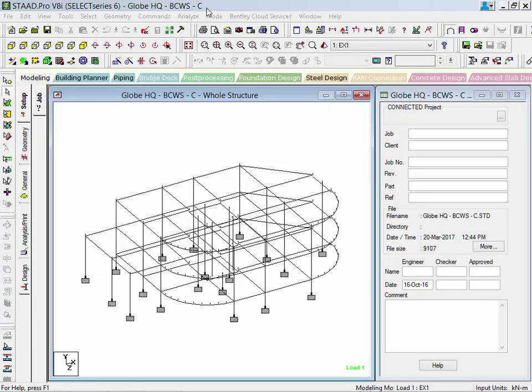beams. To begin our workflow for designing our concrete beams in the STAAD Pro Advanced Concrete Designer RCDC, we're first going to model our structure in STAAD Pro and then perform the analysis. An analysis in STAAD Pro must be performed before importing any of the model elements into the RCDC. To do this, we're going to click Analyze followed by Run Analysis.